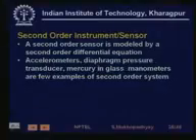Sometimes we also have to model the systems as a second order instrument or sensor. This choice can depend on which kind of model you will use. That may depend on physical reasons, or it may depend on the kind of response that you actually get from the instrument. So some instruments are assumed to be governed by a second order differential equation. For example, an accelerometer, anything which has a mass spring damper kind of representation, will have second order dynamics.